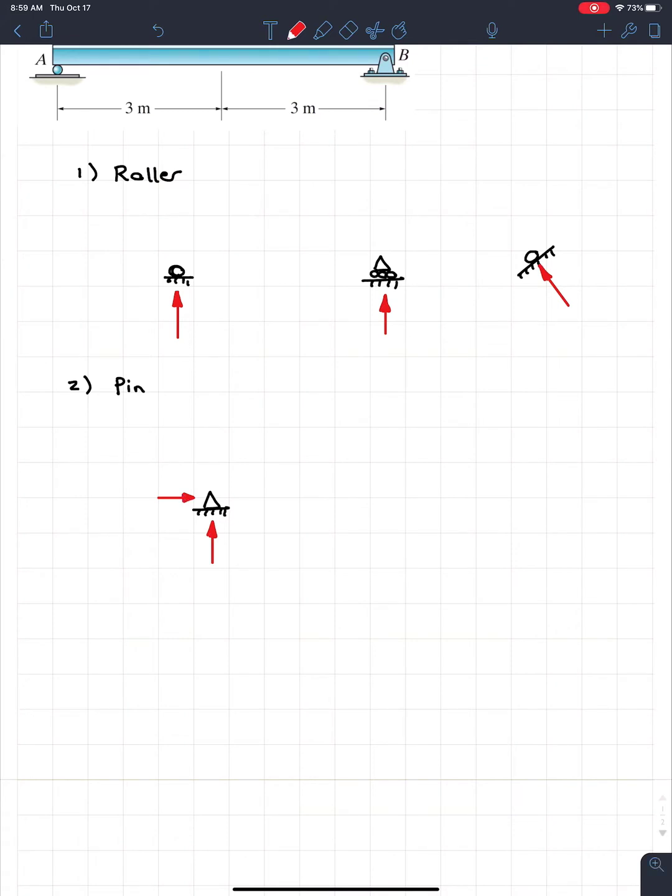And one thing we're going to discuss before we get into this is I have this pin here, and I always draw my support reactions in the positive direction. And you go, okay, Clayton, how do you know it's positive or negative? And I don't. So when you're doing these supports, you just guess. And for my guess, I always like to do the positive way. I can throw it into my equilibrium equations nice and easy. And if I get a negative answer, that's completely fine, because the magnitude of that answer will be fine. It just means I assumed the wrong direction. And it's okay to assume the wrong direction. As you will see, we'll run into that case quite a bit.